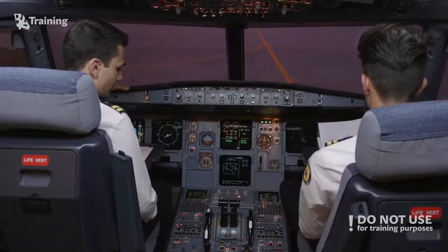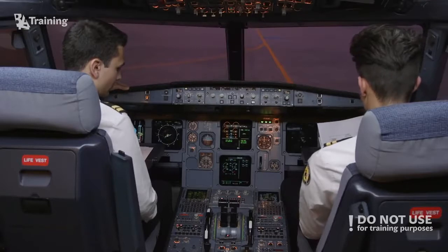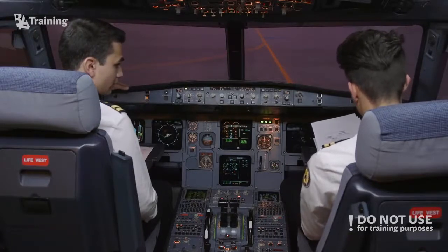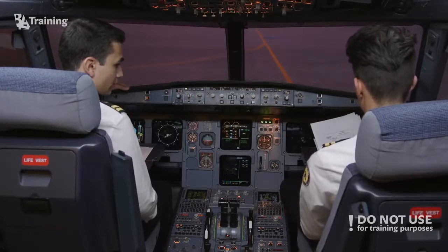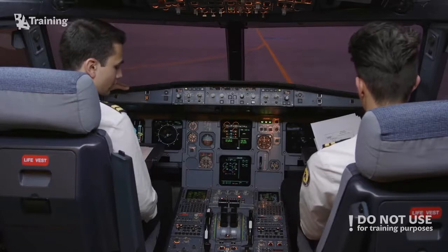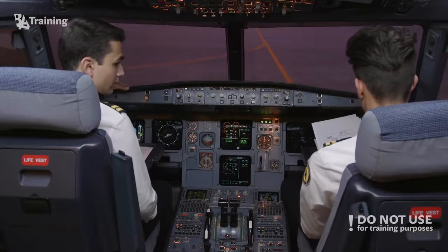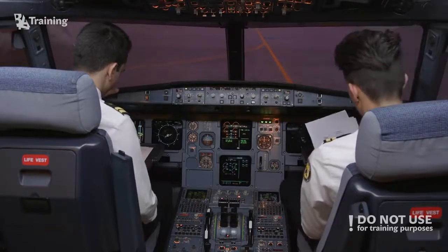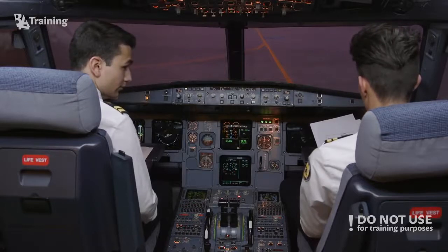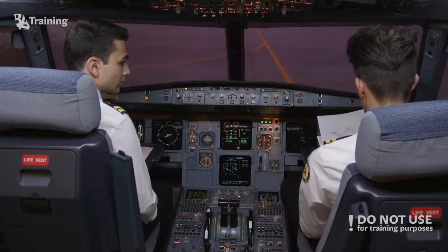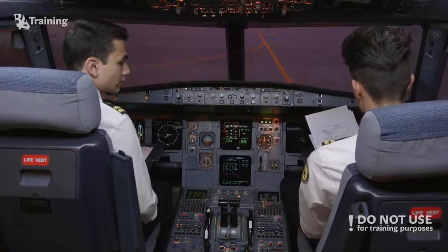When N2 reaches 50%, start valve check cross line, igniters A and B check off, main engine parameters check normal, and secondary engine parameters also check normal. Note, CFM 56-5 B1 and B2 engines, N2 accelerates slowly from 50% to idle. Start abort is not required as long as N2 increases. Engine manual push button switch off, engine mode selector normal. When no other engine requires to be started manually, shedded systems restore, SOP engine start resume.